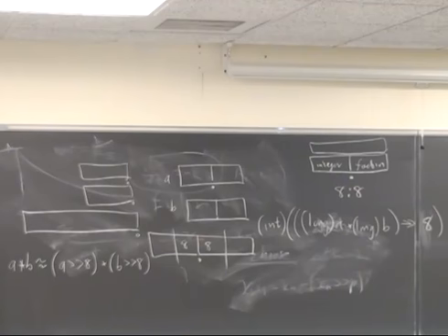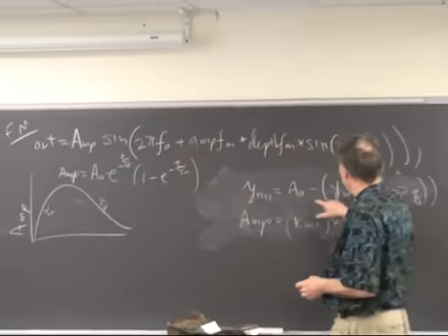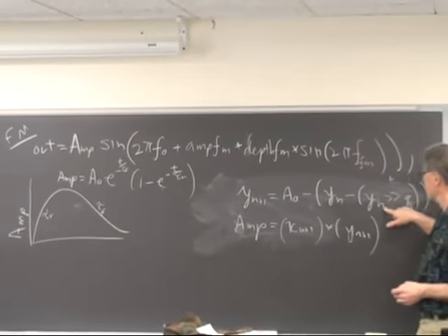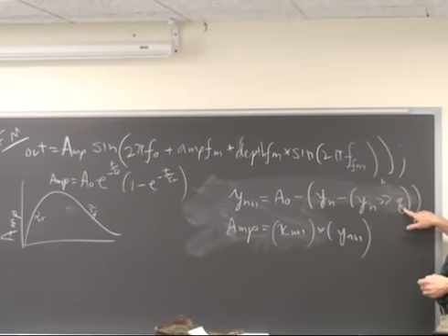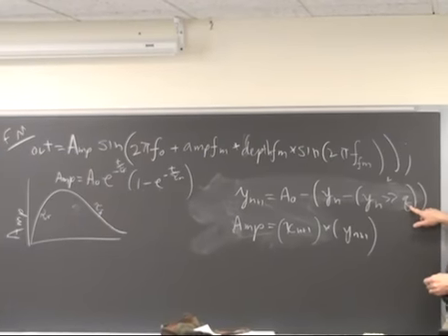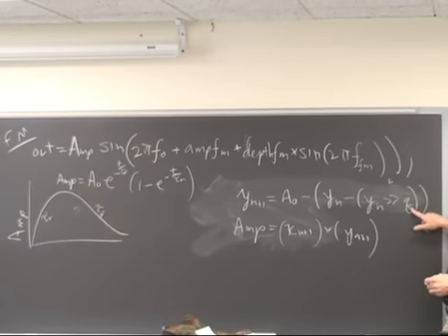Almost. Why are we using fixed point? So that we can keep enough accuracy that these calculations make sense. Because you're going to be shifting to the right by 8. If it was an 8-bit number you were using, you'd be subtracting 0 every time, and that would not be good.